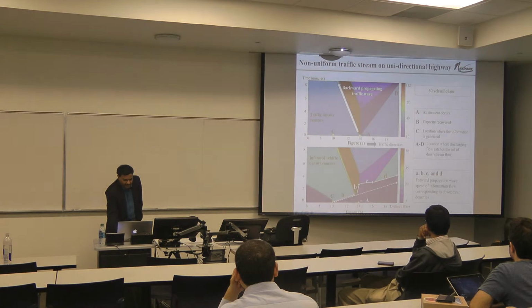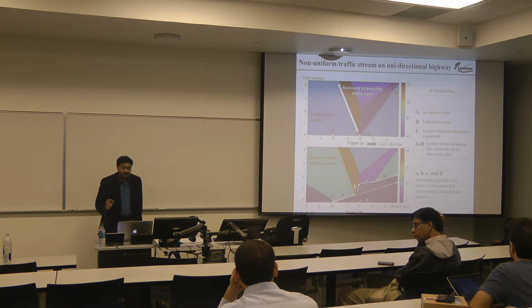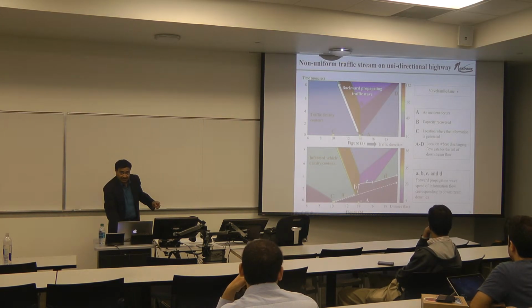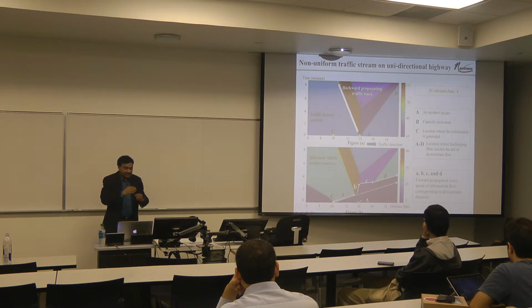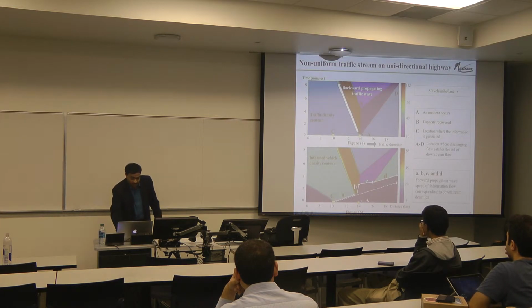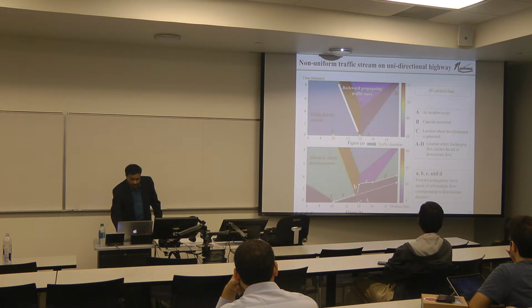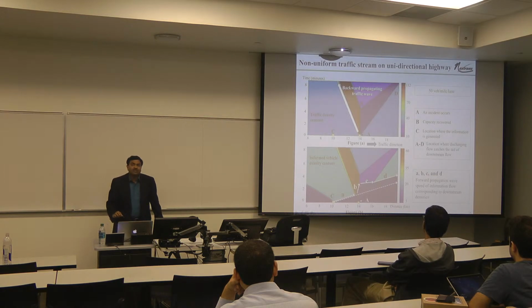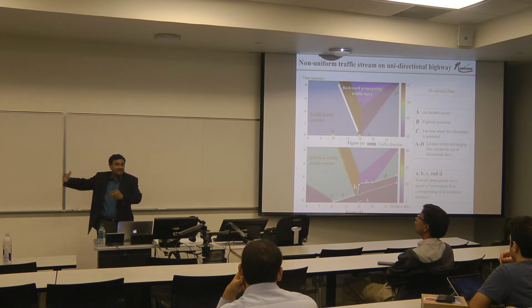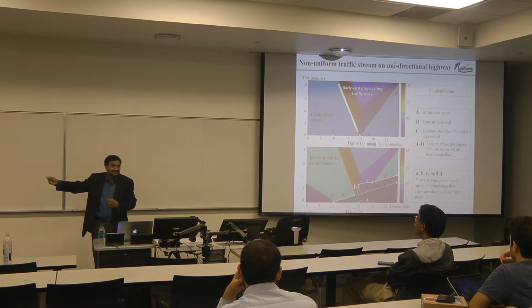Before the incident and so on, what you have is a forward propagating traffic wave going at a certain speed because the density is uniform, 50 vehicles per lane. And then once the incident starts, you start seeing the heterogeneity in density showing up. So what happens out here? The speed of the information propagation goes almost to zero. That's not surprising, because downstream of the incident there's hardly any vehicle left, right? So there's sufficient space now that the ability to communicate doesn't exist.